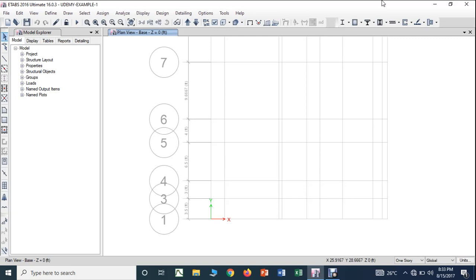Since the slabs and beams and sometimes the staircase are cast monolithically, that means together, we usually cannot differentiate, because it will be very difficult while carrying out the concreting. Therefore, we usually maintain the same grade of concrete for the beams, slabs and staircases.